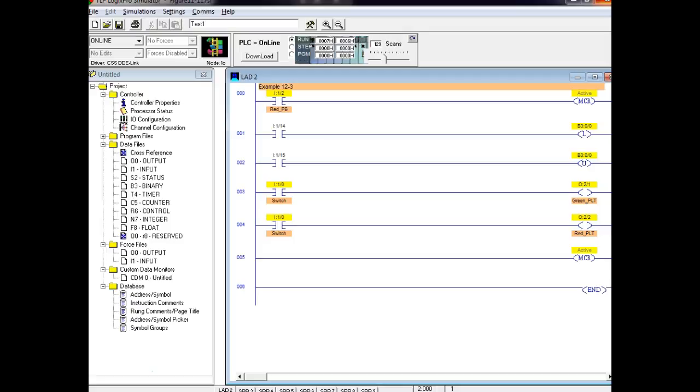You need to be looking out at what you're about to force. Any safety rules that you have for motor controls will be exactly the same rules that you have for PLC. Forcing contacts, being aware of power.